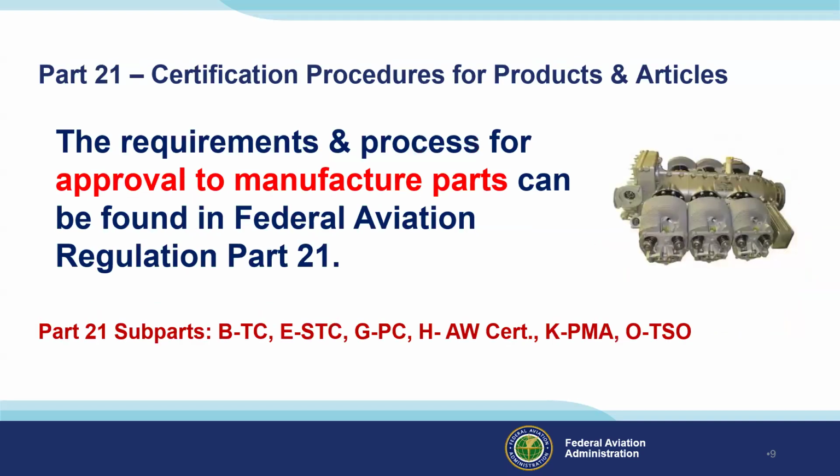Part 21 is the certification procedures for products and articles, and it gives you the requirements and process for the approval to manufacture parts. Some of the important subparts will be subpart B, covers type certificate. E is supplemental type certificate. Subpart G is production certificate. Subpart H covers airworthiness certificates. K is PMA, and subpart O is for TSO. So those are all under Part 21.